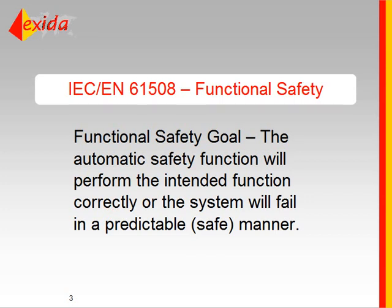So once you define these safety functions for the systems, the standard essentially helps to develop a system that functions correctly when needed, and if there's a failure that occurs, it'll fail in a safe manner. So it'll fail in a manner where it automatically alerts people that there's a problem, possibly shuts down the system. But one of the main goals is to minimize hidden failures that nobody knows about for years until suddenly a safety demand comes up.